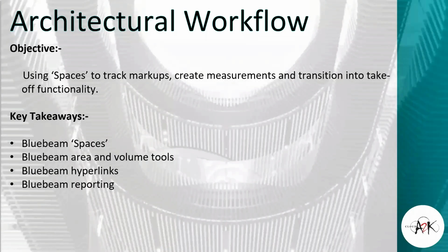Right. So now that we've done a quick one of the engineering workflow, let's do one for the architectural workflow. Okay, so let's dive into this. The objective here is to use what's known as spaces within Bluebeam to track markups, create measurements, and you can even use hyperlinking functionality. And I'll show you all of that in just a second. Again, this is another one of my favorites. The Spaces tool is not commonly known or used, and I don't know why, but it's super, super useful.